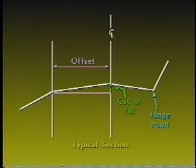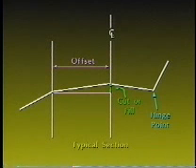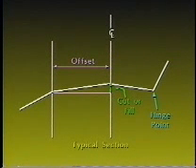Ratios and grades shown on the cross-section can be used in conjunction with offset distances to calculate cuts and fills in relation to the control line. After the typical cross-section is developed, ground cross-sections are plotted from direct measurements in the field or are generated from paper maps or digital terrain models.